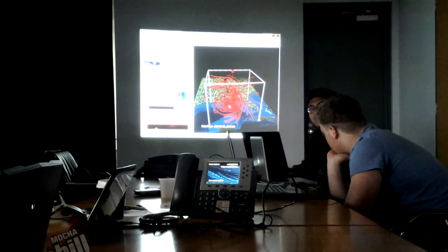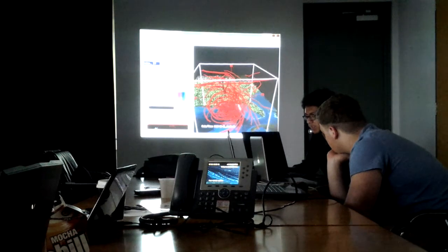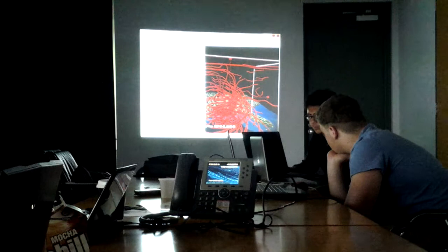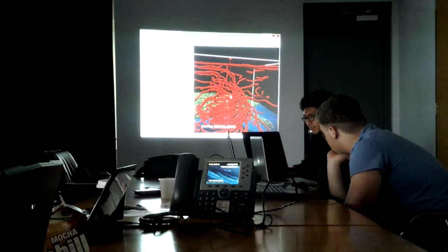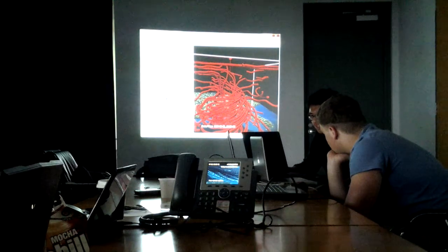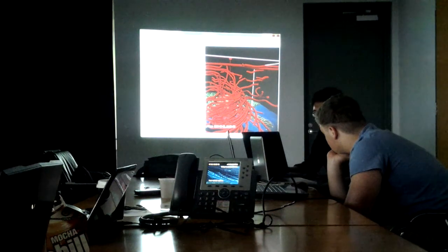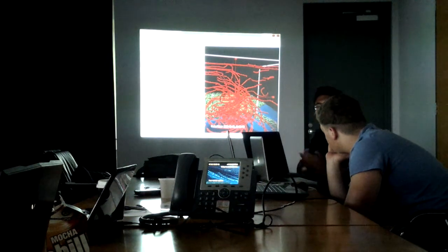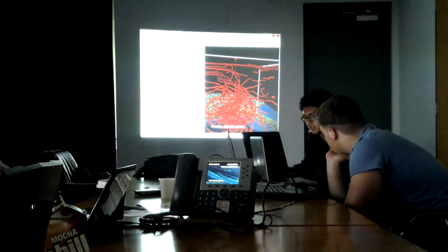Wow, cool, nice. And you can specify the direction of the airflow using arrows. So if I use arrows, the reason the arrows are so stacked is because I put the smoothness at 20, so it's calculating every small step. If I made it lower, there would be fewer arrows, but it won't be as accurate or as smooth. The line's going to be jagged as hell.